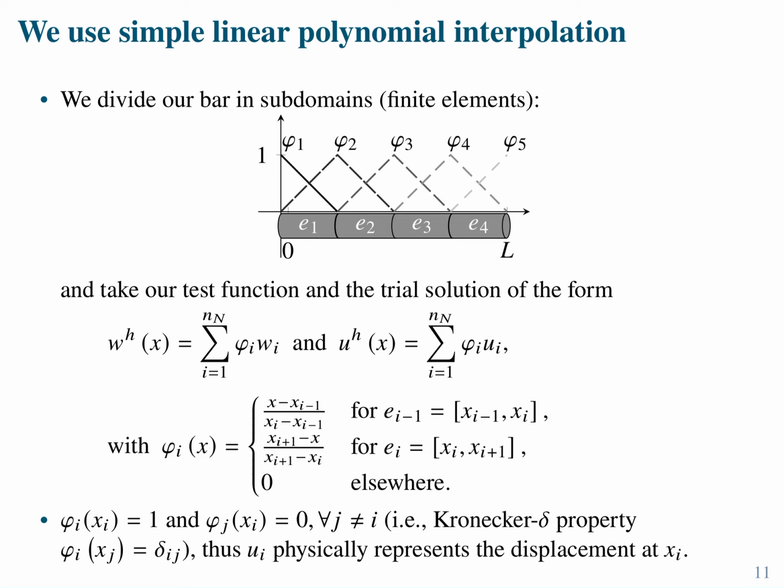Normally, when we go to more advanced formulations, that is no longer the case, right? That doesn't happen. Many things break down. Degrees of freedom no longer have the physical interpretation that you normally give. But I thought the Kronecker delta function is a requirement for a shape function. No, no. The question is whether the Kronecker delta property is a requirement for shape functions.